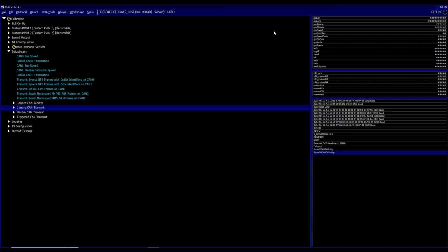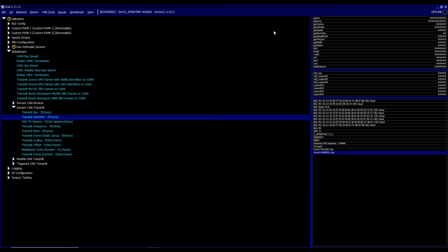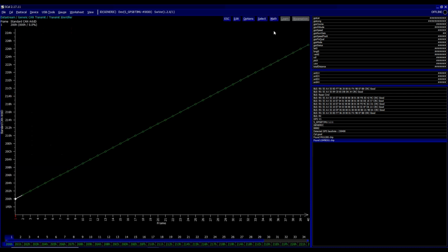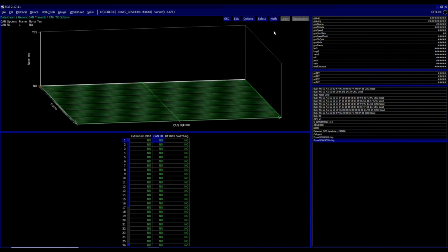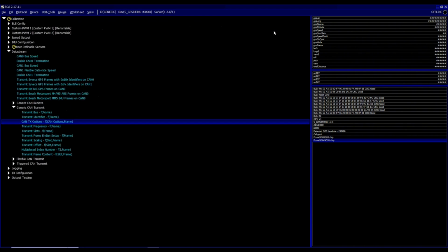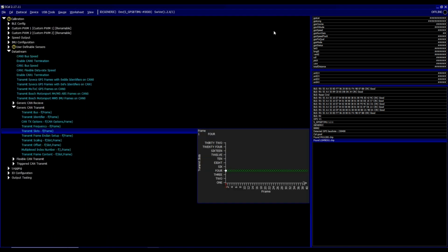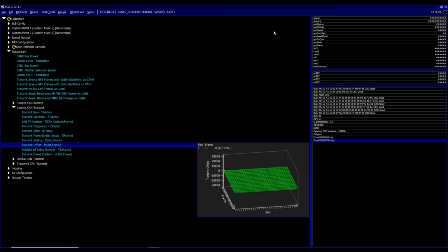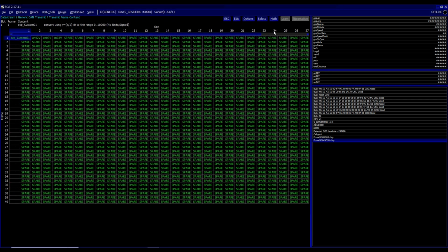The best way to do that with a Syvecs ECU, rather than using the generic CAN receive, is to use the generic CAN transmit. We're going to choose the bus that we set it on, so CAN 0, and we're going to send it on 200 hex. We don't care that it's not extended, CAN FD or bitrate switching. We're going to transmit that every 100 Hertz, and we're going to say transmit slots 4 is fine, no scaling needed, and we're going to put the ECP into the first byte there.